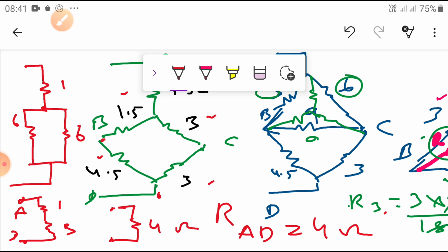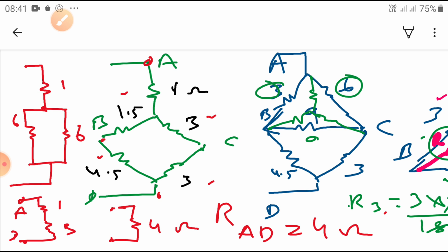Okay, dear students, it is very simple. Without using star-delta, you may find it very difficult to find the equivalent resistance. So by using KCL and KVL, once you convert the network and simplify it with the help of the star, you are going to get it.